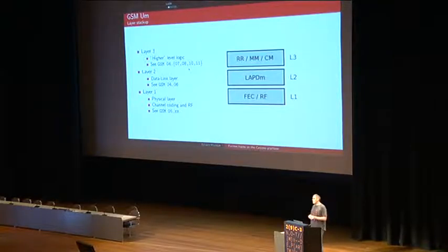It itself can be decomposed in two parts. The one I would call the channel coding. So basically, you take layer 2 packets, you add things like forward error correction, convolutional coding, CRC, things you need when you transmit data over the air and you want the data to be actually received clearly. And the second part is the actual RF part. That is, you take the bits and you somehow modulate them and transmit them to whoever you want to transmit them to.